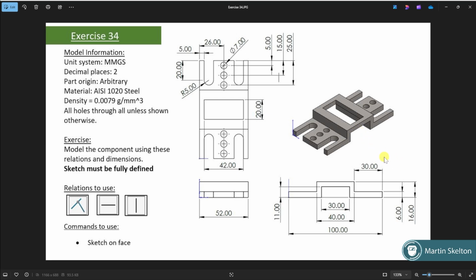Now, which plane or which view would give us the most information to start off our actual object? Well, for me, that is the right hand side. If I look in the right, I can get this image. What's so great about starting on the right? I could start in the top as well, but for some reason the right is calling me to start. If I produce this shape, I can extend it out 52 millimeters and I can get my overall shape of the whole object. And this is the kind of thinking that we want at this stage.